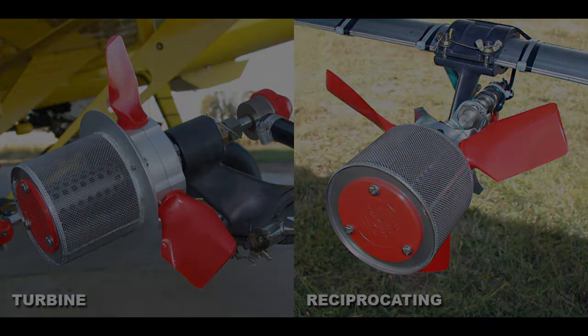The majority of forestry work is done with turbine aircraft, and the rotational speed would be higher than that for agriculture, because although in agriculture we're shooting for a droplet perhaps around 200 microns, in the case of forestry it's smaller, typically in the range of 100 to 150. Therefore, it's the same atomizer, but set to run faster.